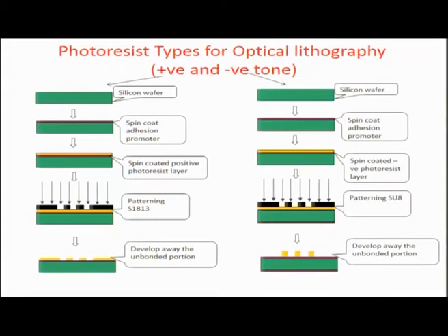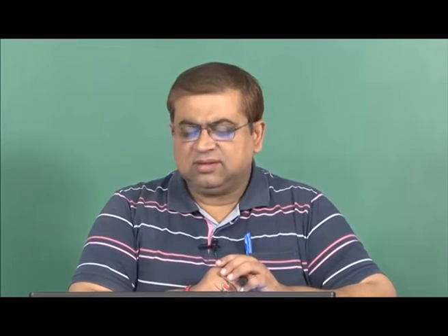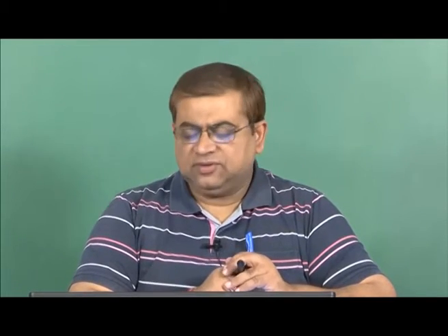So when we are talking about photolithography, it is a process of selective exposure, like photography, through a black and white transparency or mask, of a photoactivated chemical which is known as photoresist. The advantage that photoresists have is that they undergo chemical transitions when exposed to certain wavelengths of light. Those transitions could be debonding effects or bonding effects, and there are various photoresists based on whether they debond or cross bond on exposure to light of a certain frequency.